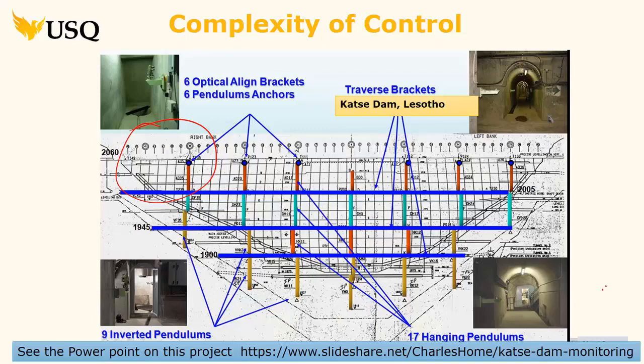You can see a bracket up here at the top left with a double theodolite on it, a double barrel theodolite. Pendulums hang everywhere and are measured regularly, because at the time this was built, the internal geotechnical data was expensive to collect. It's getting cheaper now. So that was the internal side.